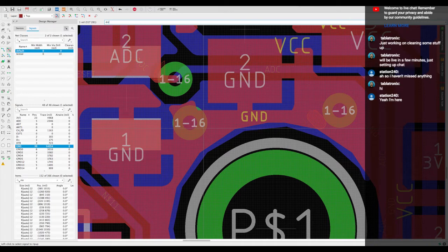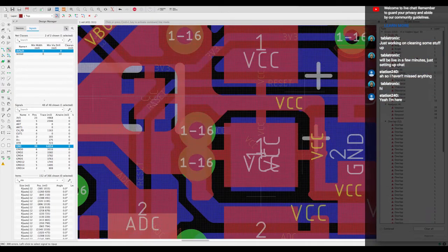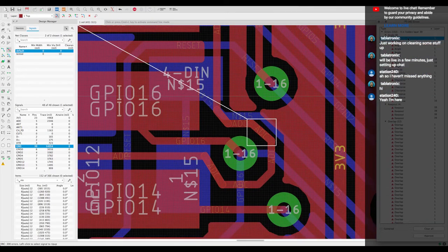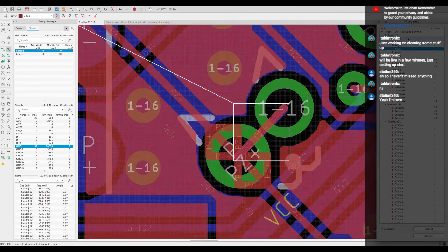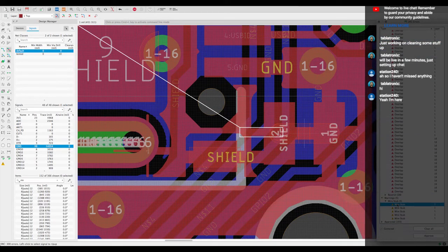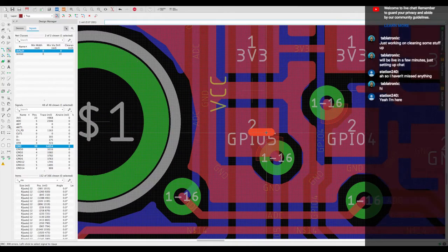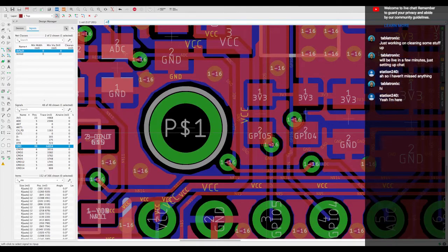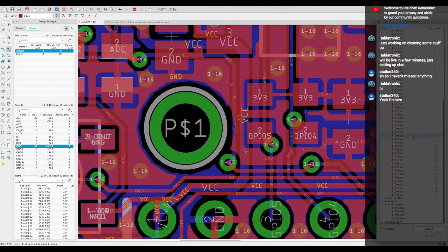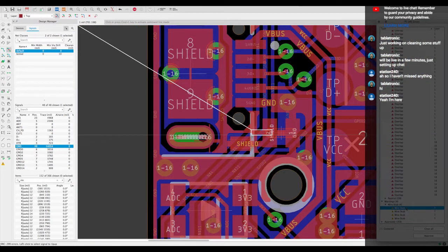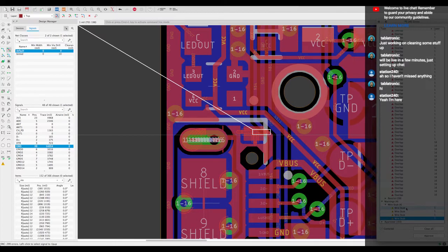A wire stub is basically something that's not connected to something else. It's just a dead trace. So you really want to stay on top of those, but sometimes you have them on purpose. You just delete them. Make sure you don't delete... Sometimes when you delete a wire stub, it will delete something else.